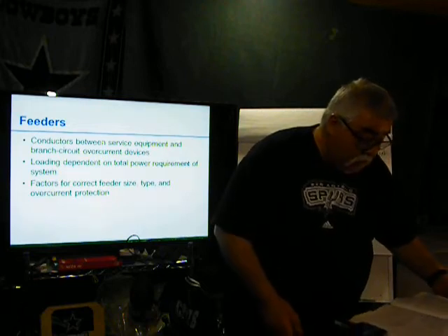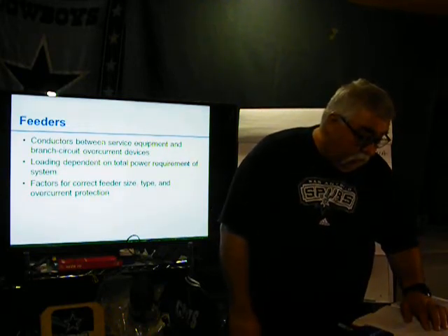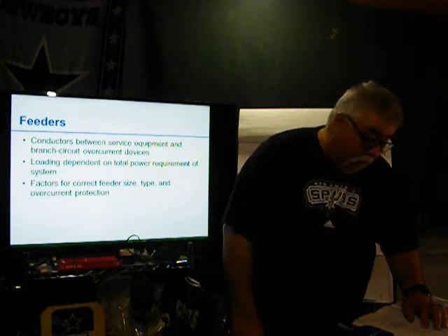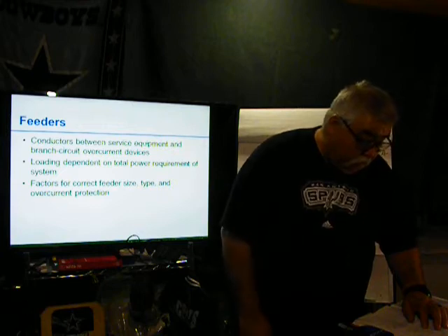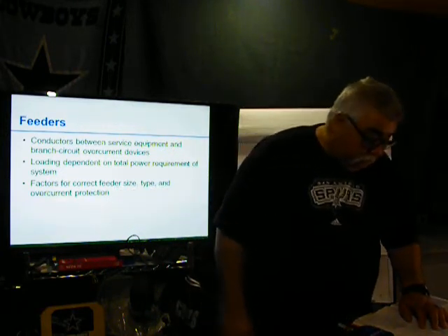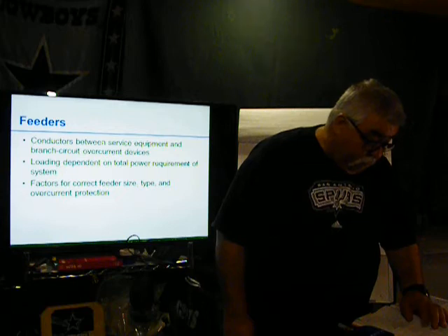The length for voltage drop, I talked about that. The derating factors. Conductor size includes several factors: conduit fill, ambient temperature correction, and load demand. So that's the correction factors. The neutral wire may not be necessary with a feeder.